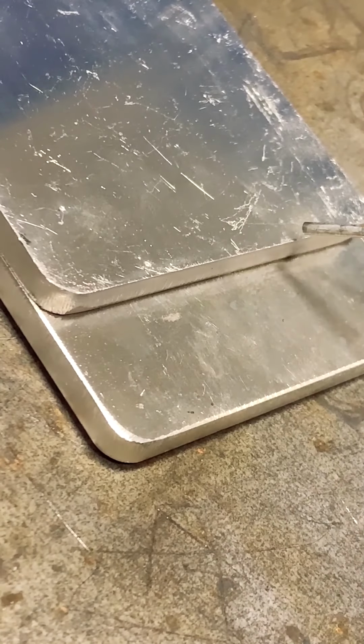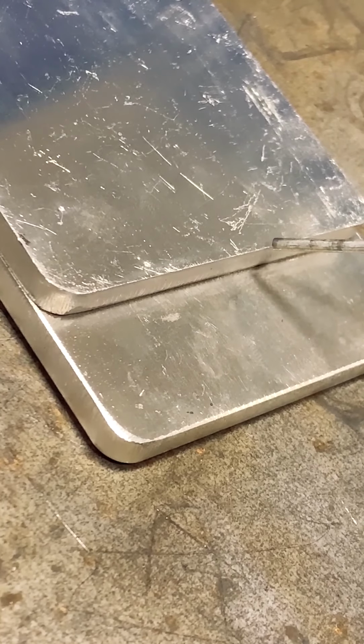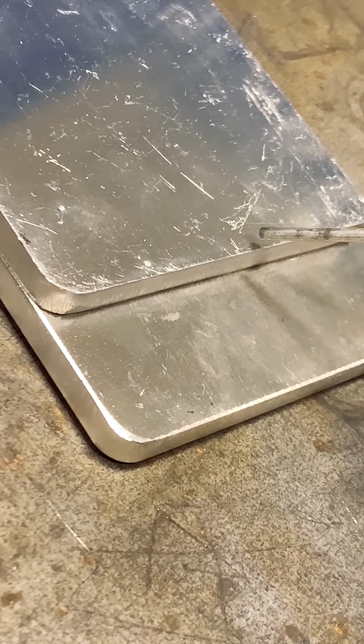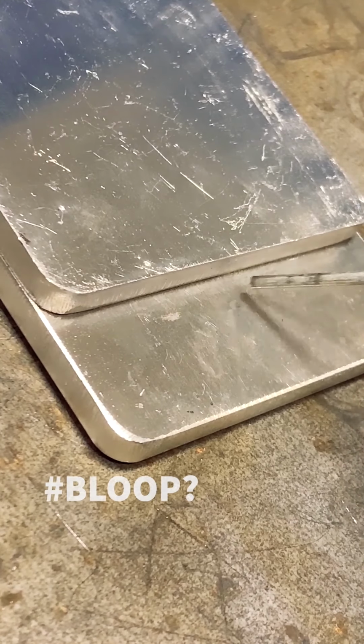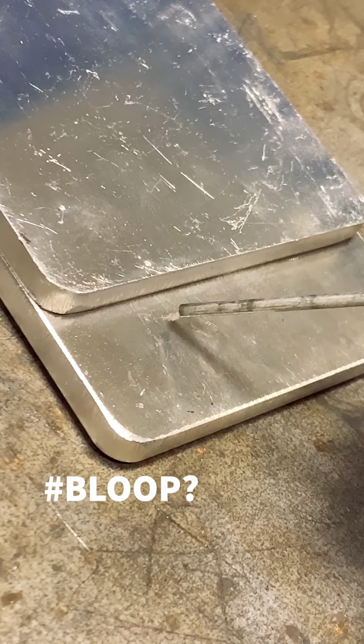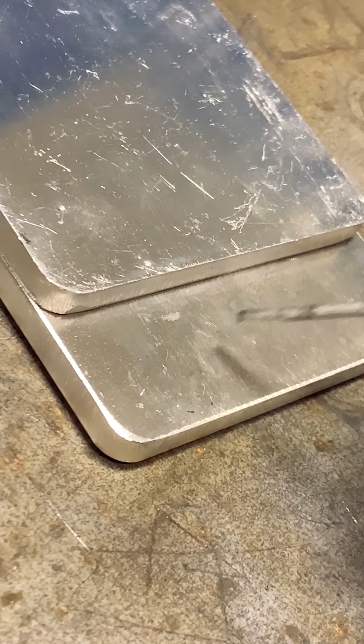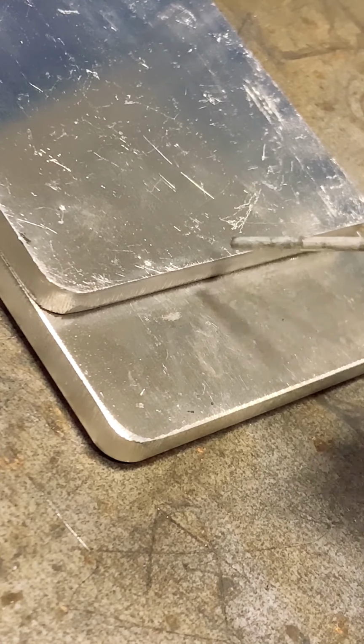Specifically in this lap joint, if I have my electrode too high on this top piece of metal right here, I pull too much of this material, and gravity takes hold and bloops it on down here. So I should be able to see that I'll get some cold roll or some overlap on this bottom toe of the weld, and I'll undercut really heavily here.